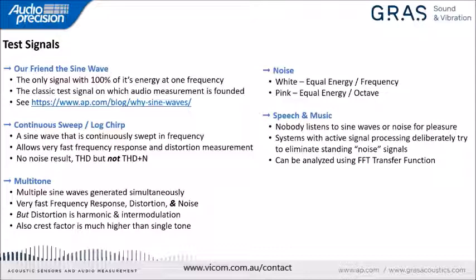But the results are a little complicated because we're capturing not just the harmonic response, but the intermodulation response caused by playing all those signals simultaneously. So there is a noise and distortion result. Unfortunately, it is not directly comparable to the results we get from a single tone sine wave.